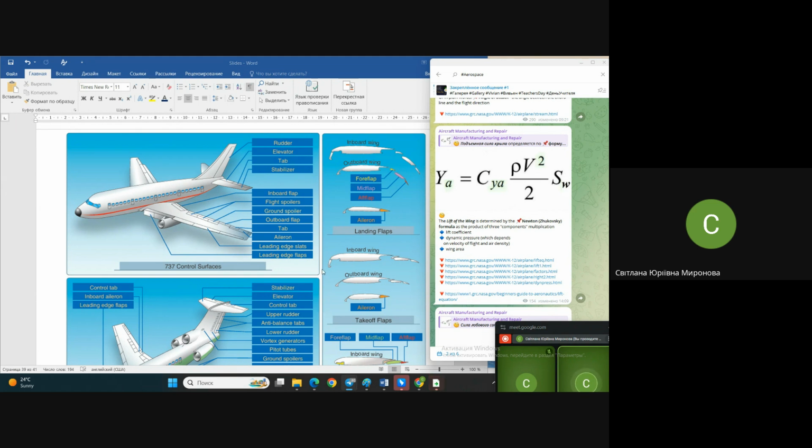But pay attention, during takeoff, when you need maximum lift and minimum drag, the flap is practically horizontal, and it increases the area. It increases the curvature above the wing due to the slats. Also, you see the slats are deviated significantly, but not so as to create much additional drag. And during landing, in contrary, they do what? They increase both lift and drag.